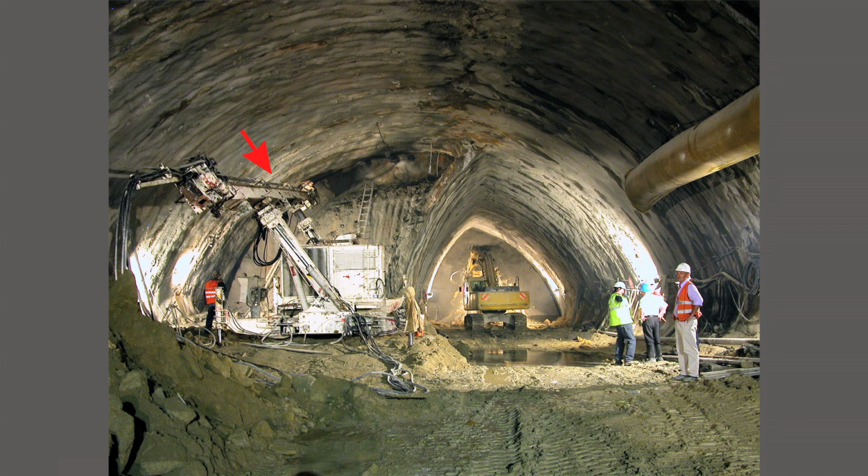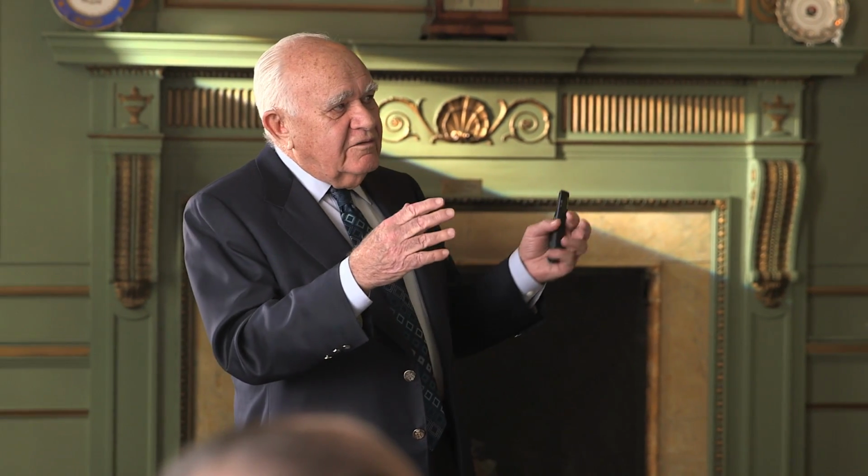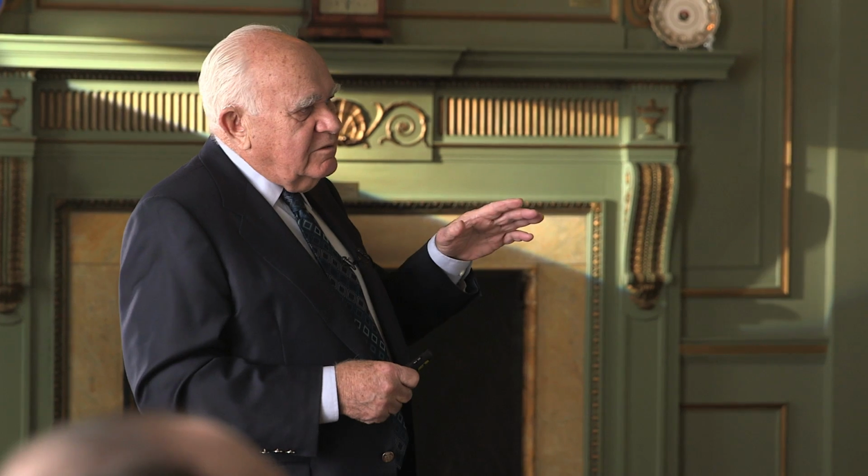But what was done in this case is that the first step in the process was to drill, as you see on the left-hand side here, 12-meter long holes into the rock above the cavern you're going to create, and to flush the soil out of those with high-pressure water, and to fill them with grout, with cement or concrete, so that you are forming an umbrella of closely spaced holes of concrete, and a concrete arch over the face. Because not only do you have the roof trying to fall in, but the face is also coming towards you because it's unstable. So that protects the face, it enables you to get in then, and now you can do your pilot tunnel through that protected area, as you see on the right.